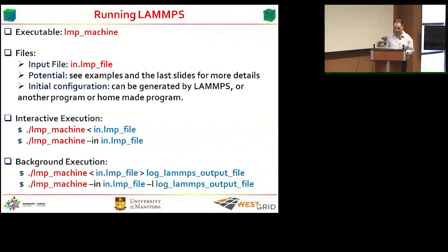If you want a configuration with BCC, FCC, or HCP, there is a very limited number of structures that can be generated using LAMMPS. Otherwise, you have to use other software to generate the initial configuration, or write your own program to generate it, then adapt it to the LAMMPS format. Now to run LAMMPS, just type your executable